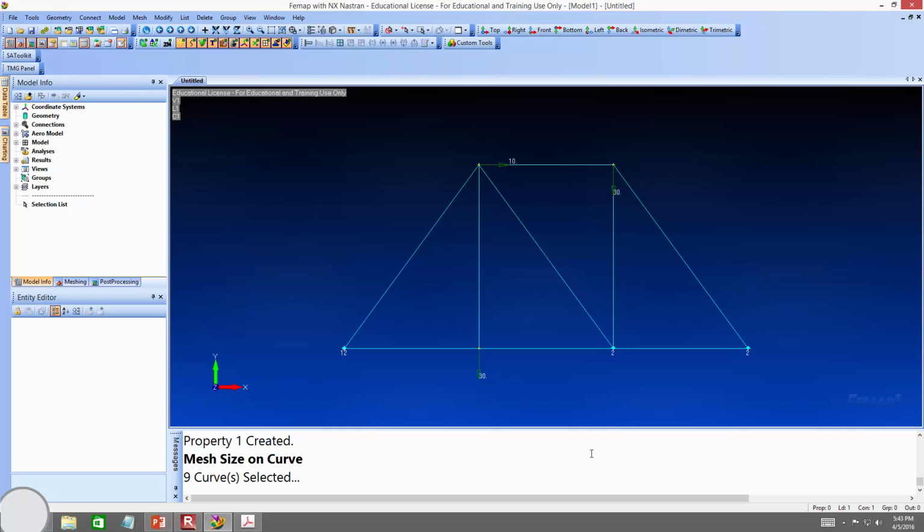If you're doing something like a 3D bridge analysis and you're trying to figure out how the bridge behaves when it's curved and skewed, and you're placing the wet concrete on there and looking at things like the cross frames and the diaphragms, you actually do need to use like 5 or 6 elements for those diaphragms and cross frames, because that stuff gets complicated real quick, okay? But for this, no big deal. All right? Make sense? Okay.